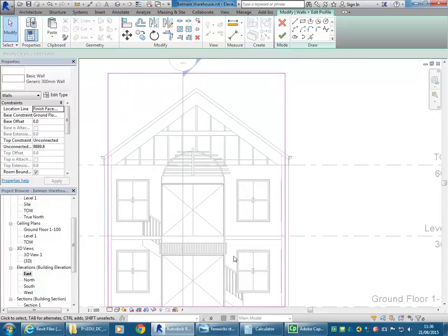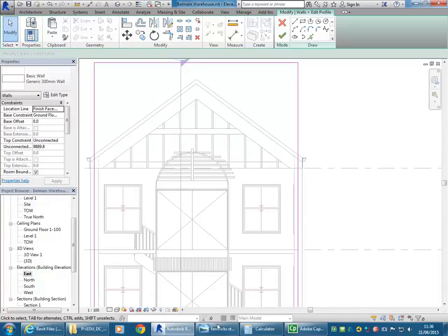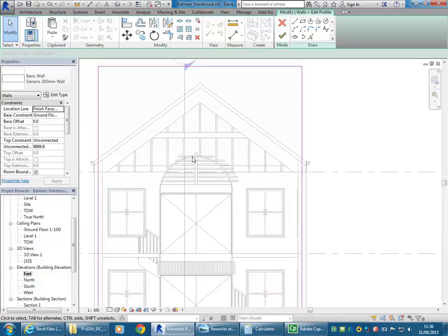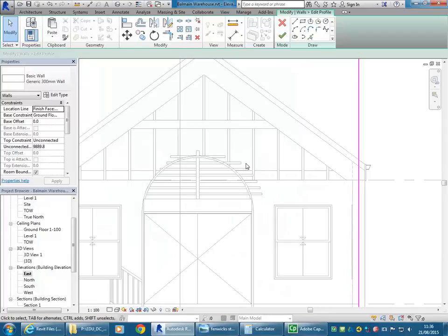And so then remember we were saying that the line of the first step there basically comes from the top of that arch. Yeah. And then it's set down, and of course these caps are a different size, but no, it is set down a course. So we're going to say the courses are 350. So that tells us everything we need to know to get started. So like I said, if you just want to watch this bit, and once you get the basic idea, you'll be able to do the rest.